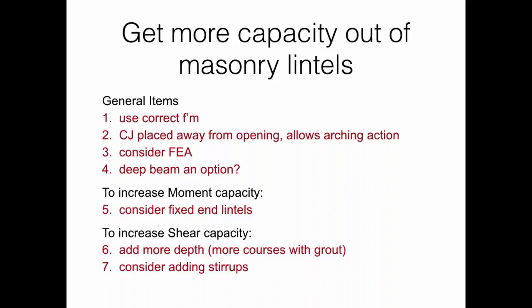Consider FEA. FEA is going to capture that arching action, right? You can see it from the slide. You can see the arches occurring within the stress contours. Deep beams are certainly an option. We didn't have a chance to talk about that, but you can use the full depth. When you talk about lintels over openings, I can use the full 20 feet of depth to design as a lintel. It doesn't have to be grouted solid. We have a lot of options that we can look at when I'm spanning over openings.